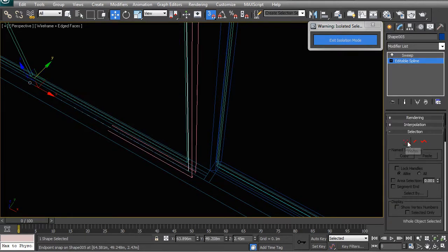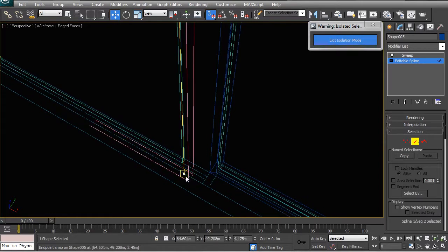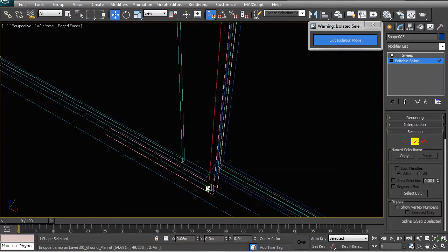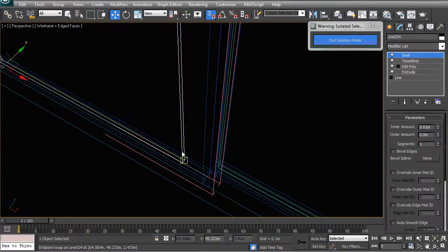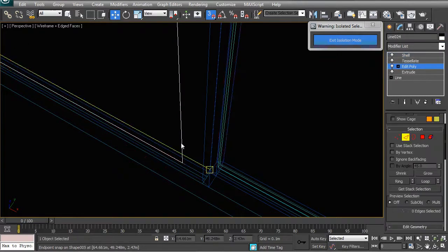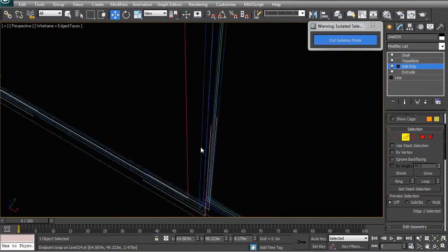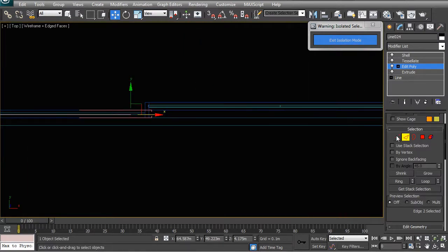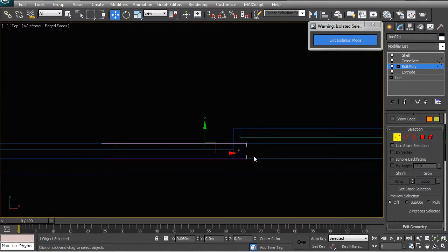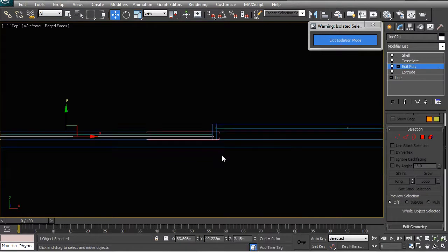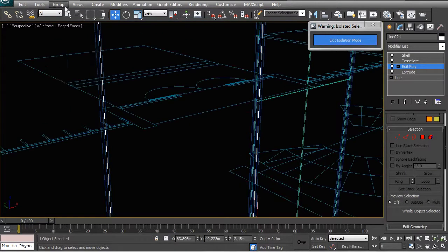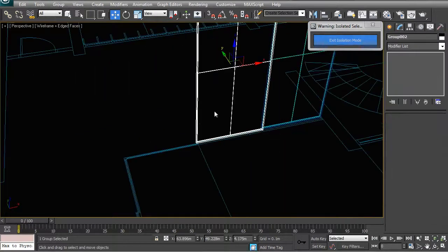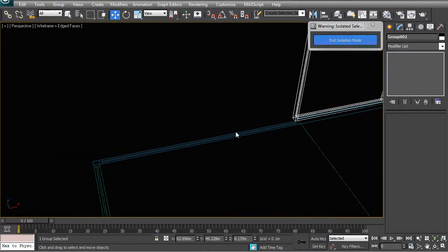As soon as it's selected, I'm going to grab that outer edge and snap it onto the outside. And the same thing with my glass, I'm going to move that slightly outwards. You can also do that in plan. Just move that into the frame, close my group back down again, and then repeat my copy command.